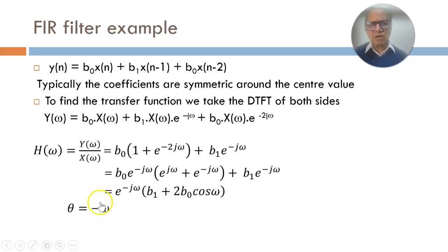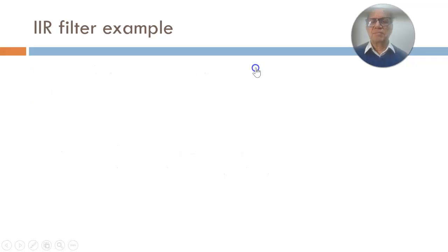And if you recall, in one of our earlier lectures we had told that if we don't want the signal to be distorted, then magnitude response should be uniform within the band of interest, and phase should be linearly related to the frequency. So which is indeed the case for the FIR filter. Okay, now we will show that for IIR filter the phase is nonlinear, again by taking one simple example.